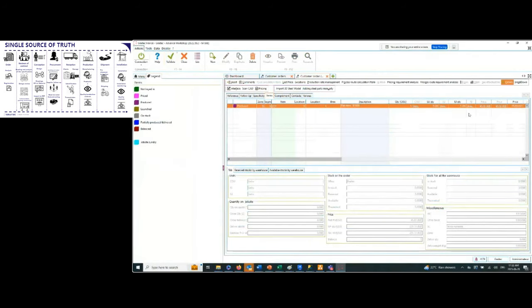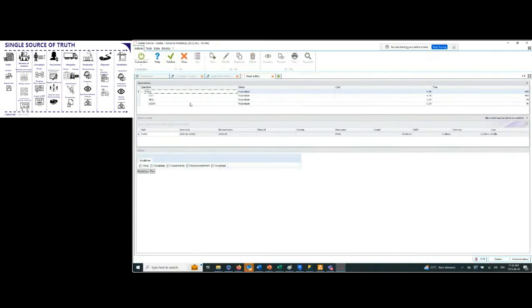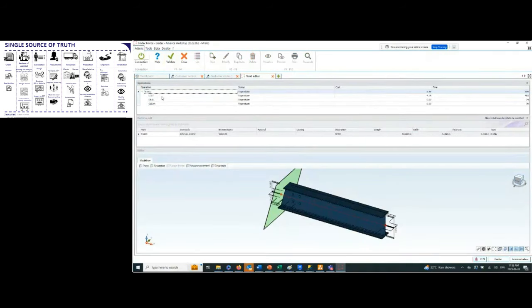And once again, here, if I go back to the steel elements, we'll see the additional operations allocated here. And the price per operation as well, and this is based off the theoretical time per operation. So the theoretical time per operation, I should also mention that this takes into account machine setup time, so just actually placing the beam onto the machine if it's a beam line, and then running its operations, okay? So that's an important point to mention.